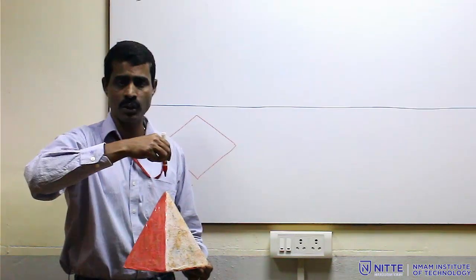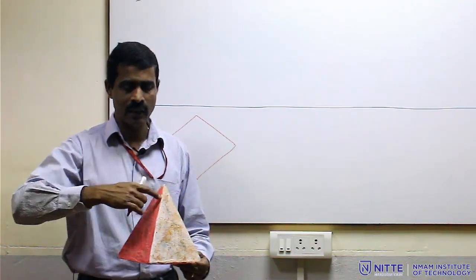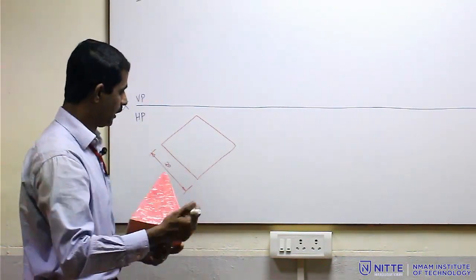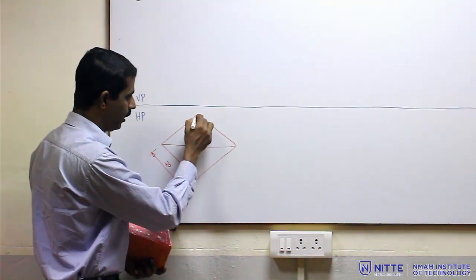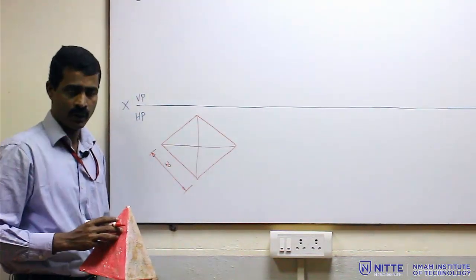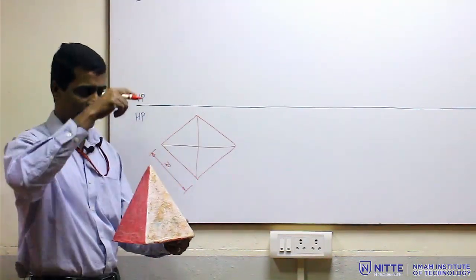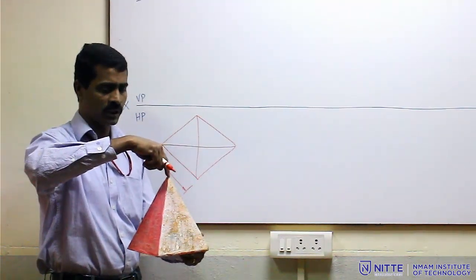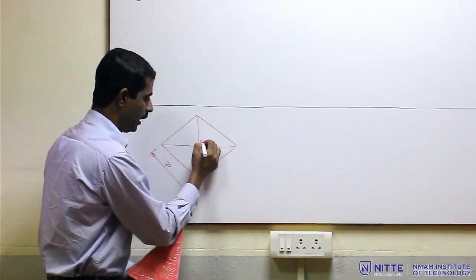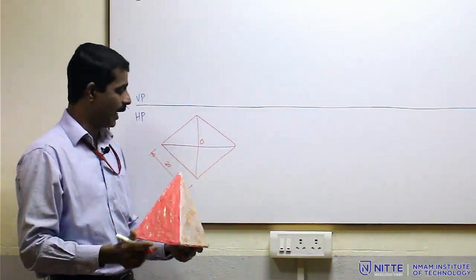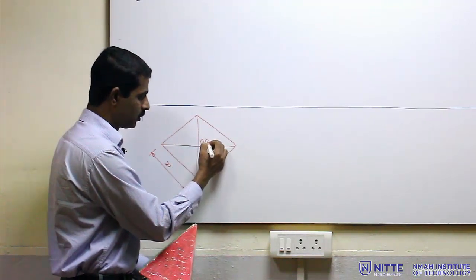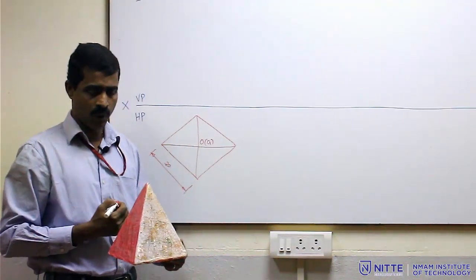And the top view not only that much, when we see from the top we can see the slant edges. So, that is why for a square we are supposed to draw diagonals to obtain the center point, and this point when you see from the top, the first point you see is the O apex, and where is O1? O1 is exactly below that and the same point it is, so O, bracket O1.